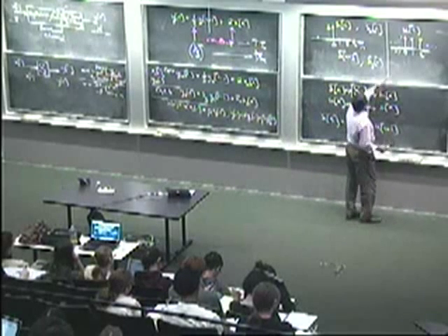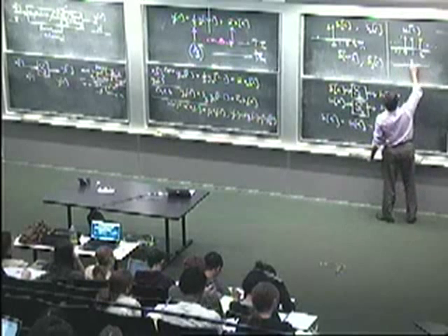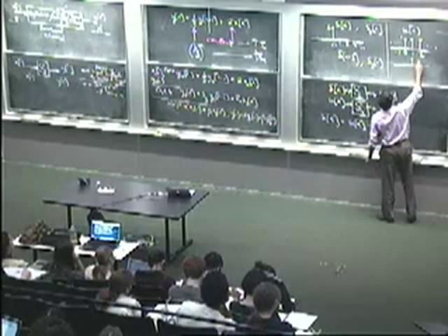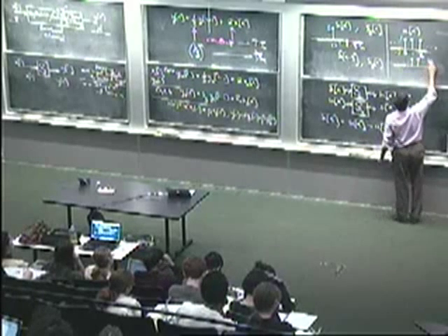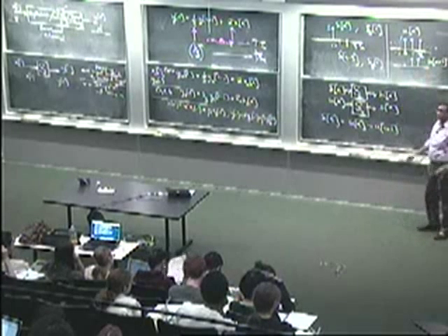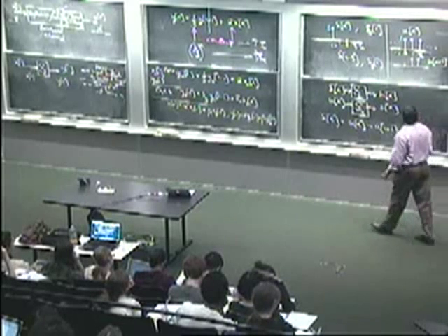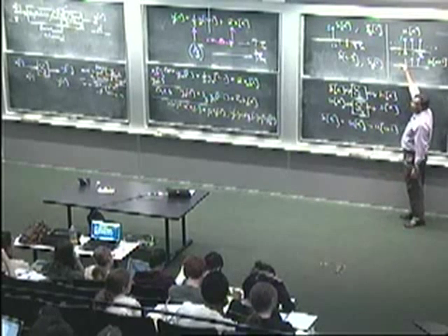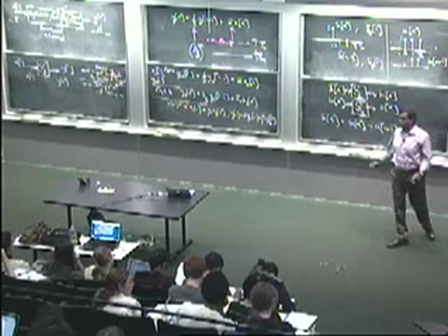So what we're saying is, take this unit step and then subtract from it a unit step delayed by 1. Okay, so here is u of n minus 1. If we took the unit step and subtracted from it a delayed unit step, delayed by 1, the result will be just that value 1 at time 0 will survive, everything else will cancel out. Right? Is that what you had in mind?